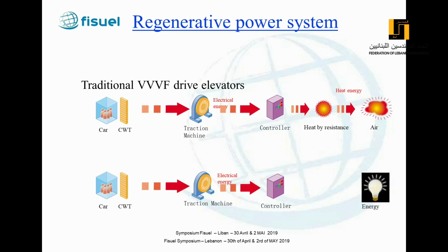Traditionally, what will any VVVF drive elevator do with the generated power? It will dissipate it in a resistance as heat. What if we use this energy back into the grid? This is the regenerative power of lifts. Now, this information will be detailed by Connie.